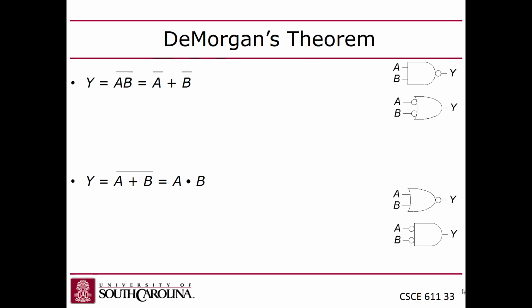And also, you can use these rules to do things like reduce the critical path of your circuit, which changes its timing spec. Or you can use it to balance a circuit. You can balance the paths of the circuit if you want to try to eliminate glitches. You guys with me? So the idea is these rules allow you to transform a Boolean expression into an equivalent form that gives the same truth table and has the same behavior, but it changes the hardware needed to implement it. So these rules are actually more important than you might have thought when you first saw this in 211. And I have a pretty neat example of that I'm going to show on Monday.